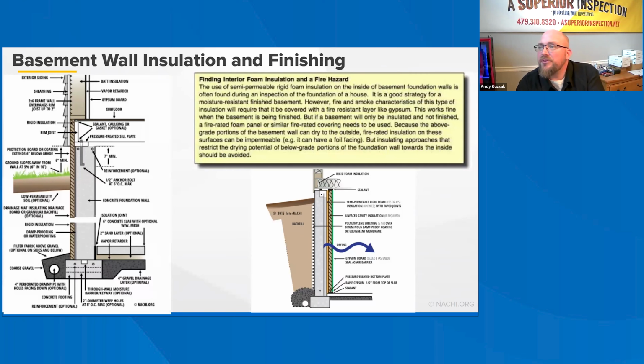Due to inspectors working with both new and existing constructions, this discussion focuses on interior insulation systems for basements. Exterior insulation strategies, such as using foam insulation panels on the outside of the foundation wall, remain viable options for new construction. These panels provide a moisture-resistant insulation layer exterior to the wall, moderating the interior wall surface temperature and integrating with waterproofing or damp-proofing. This requires shifting the house structure outward so that the sill plate protects the upper edge of the foundation insulation during and after construction, which you can see over here in this diagram.